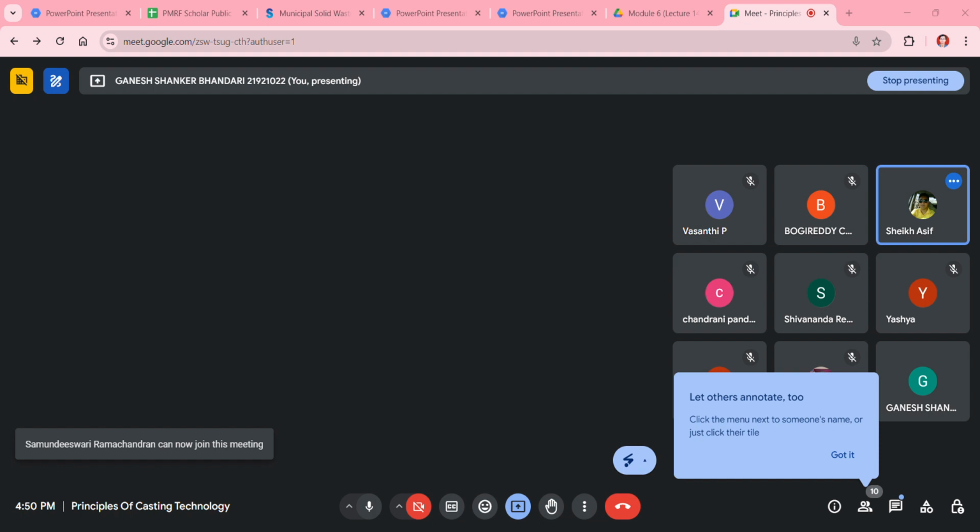You have to go to one haul container. You will pick up that haul container, and you will dispose it off at the disposal site. Then you will go again back to the second haul container, then third, fourth, fifth, sixth. So providing 57 trips per week, you have to make at least 8 trips per day. So that is H. How many trips you are going to do per day? That is your H.